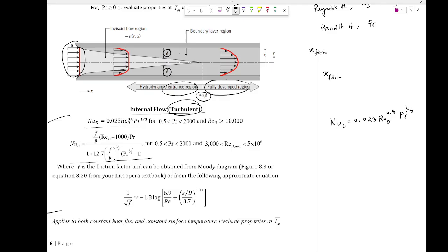Now this Reynolds number here, the critical Reynolds number, depends on the source. Remember I was saying that in Cengel it is 2300, in another book it is 3000. Some other publication, maybe I'm going to write a book next year and say no, it's not 3000, based on this journal, 3200 I like, and it's not like I'm claiming it out of nowhere, I'm going to refer to it. So yes, this happens. All I'm trying to say is you have these two equations for the same application. If the second one feels scary, and I don't specify, use the first one.